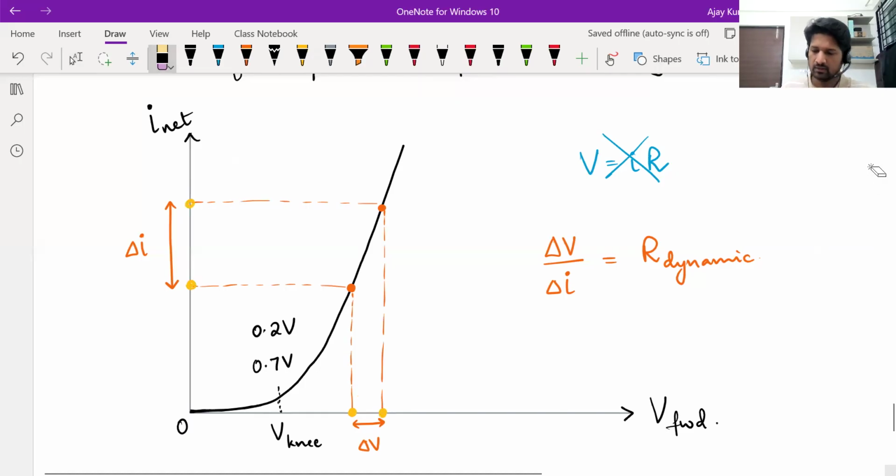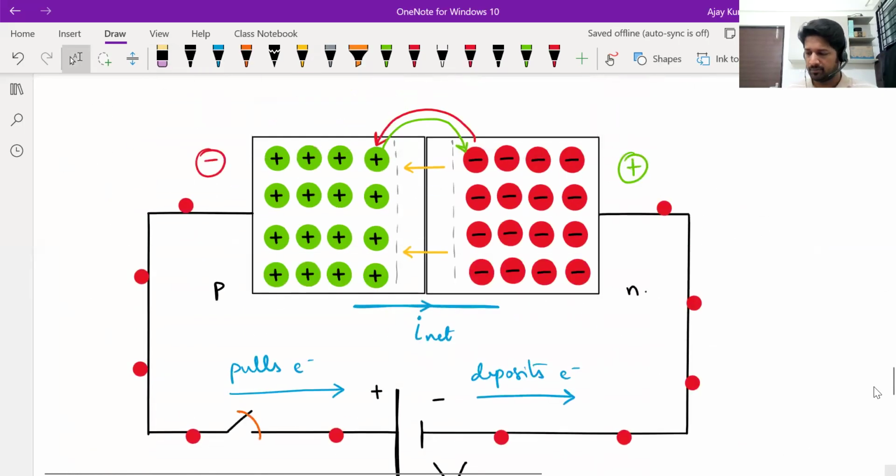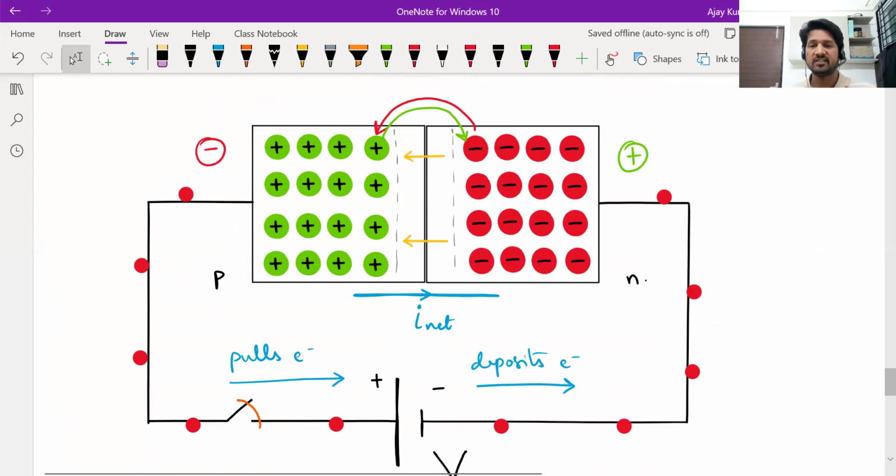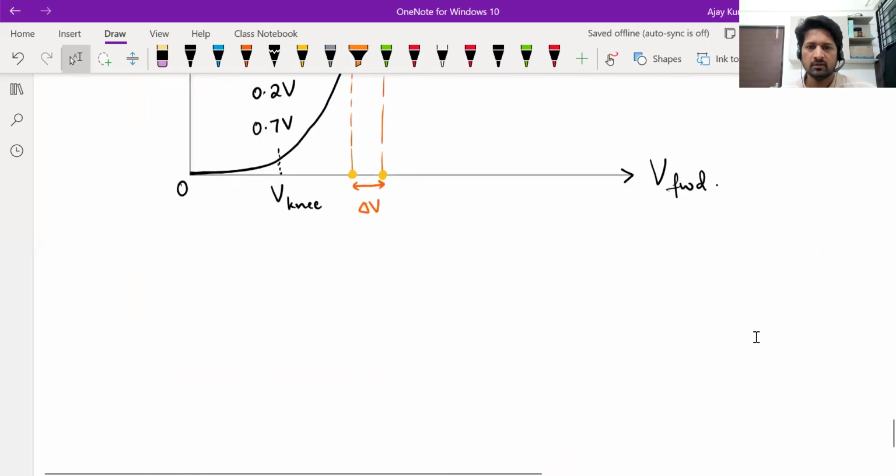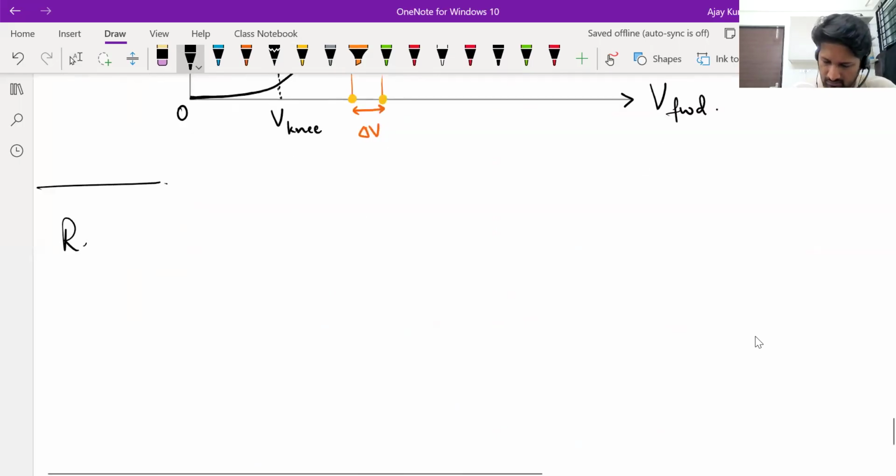So why is there significant current in forward bias? Because forward bias favors diffusion, and diffusion is due to majority charge carriers. There are a lot of them which participate in this process. And remember, in forward bias, you will be weakening the electric field in the depletion region. If the electric field is weakened, the potential barrier is lowered. Fine. Next, reverse bias.